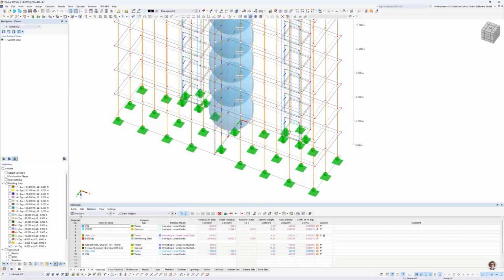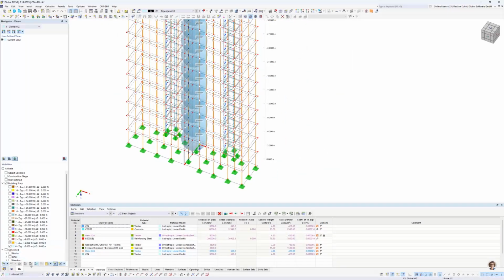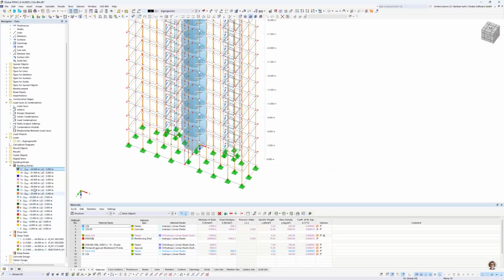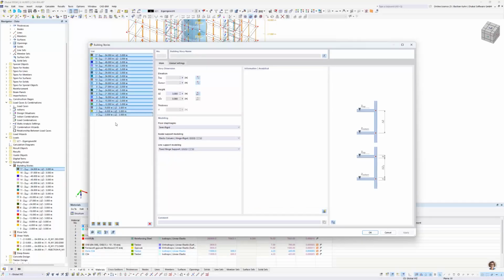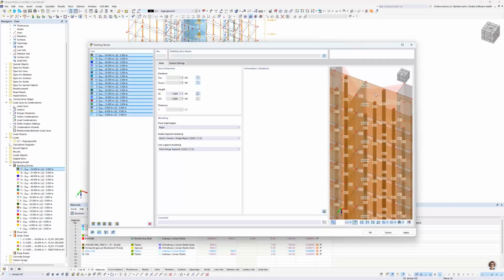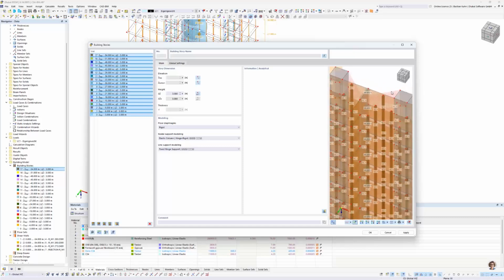All right. Okay, so this we could now calculate with the semi-rigid stiffness again, but I don't think it's of so much interest, because I want to show you also the floor diaphragm rigid. The rest I leave all the same, but when we turn on the rendering, you see that by defining the floor diaphragm rigid, you see these little red dotted lines in here.